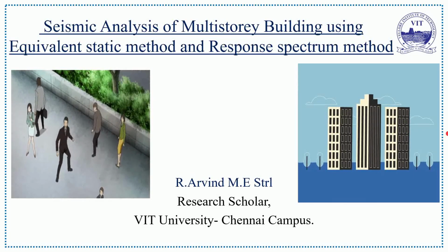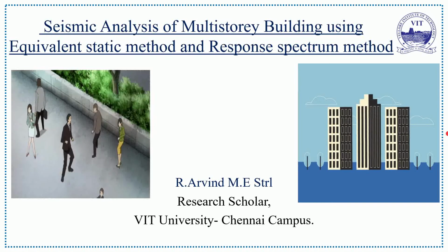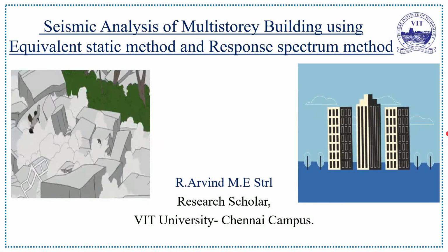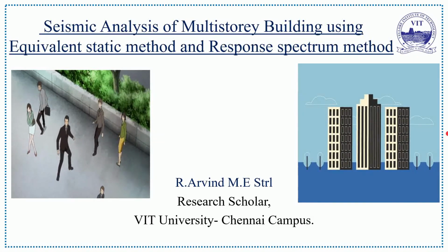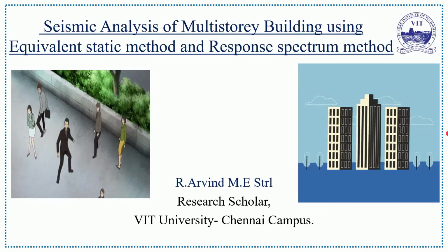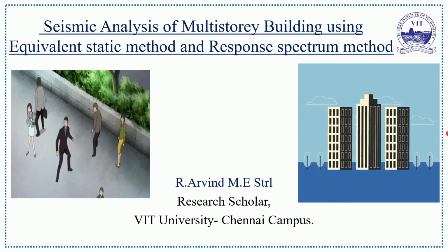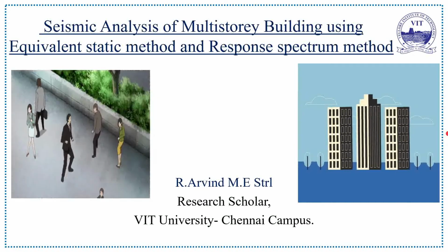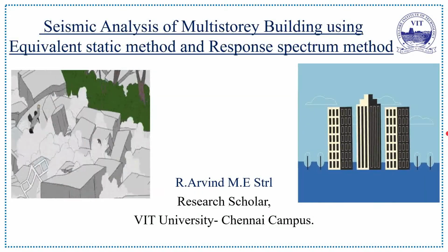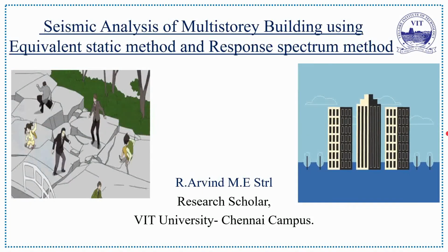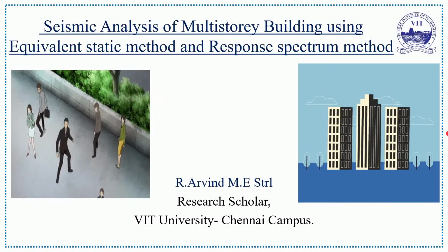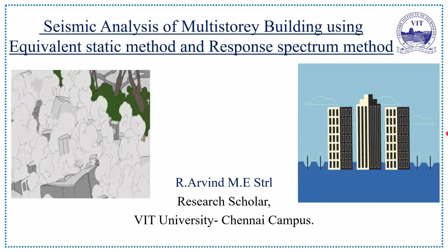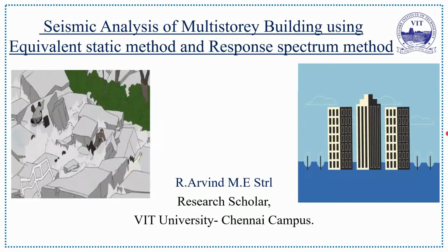Welcome to the tutorial on seismic analysis of multi-story buildings using the equivalent static method and response spectrum method. Buildings designed by IS 456 considering only the gravity load would collapse during an earthquake. But when you consider the seismic loads as per IS 1893 and give proper ductile detailing to the building, that building could withstand the earthquake force. So in this video, we are going to model and analyze using the equivalent static method and response spectrum method.